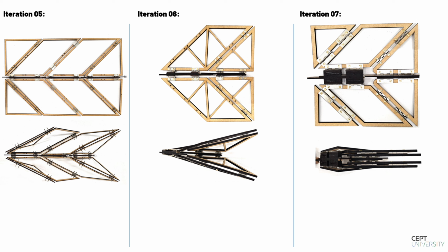Learning from iteration 6, I addressed the core issue by adjusting the geometry itself: reduce the size of the second panel by an amount equal to the size of the material and the thickness of the hinge pipe. Reducing panel size caused insufficient space for hinge placement, so I extended the central strip, adding protrusions to support hinge connections. This dimensional adjustment allowed the entire system to fold seamlessly.